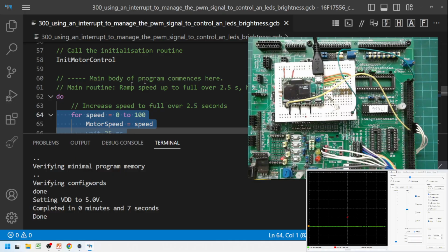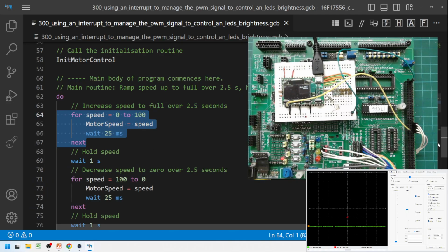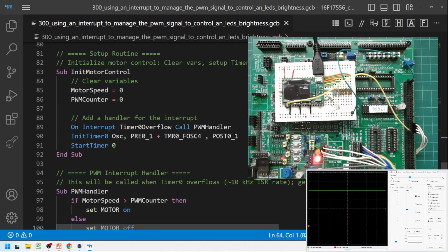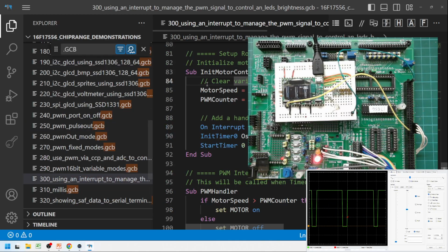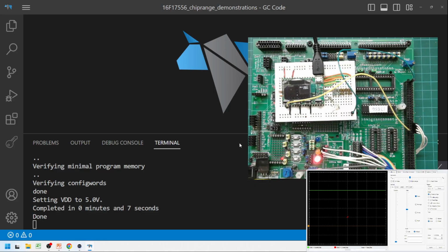No signal. Why is that? I mentioned this previously. PPS is controlling the output port. I unplug the power, which resets the PPS back to 0. I plug it in, and voila, the signal being generated for a motor is working perfectly, no PPS. I don't have to go into the details of how this is working because I'm just showing you that you can use a timer to generate a signal and you can control a motor from this. I will leave that with you for your own delight.